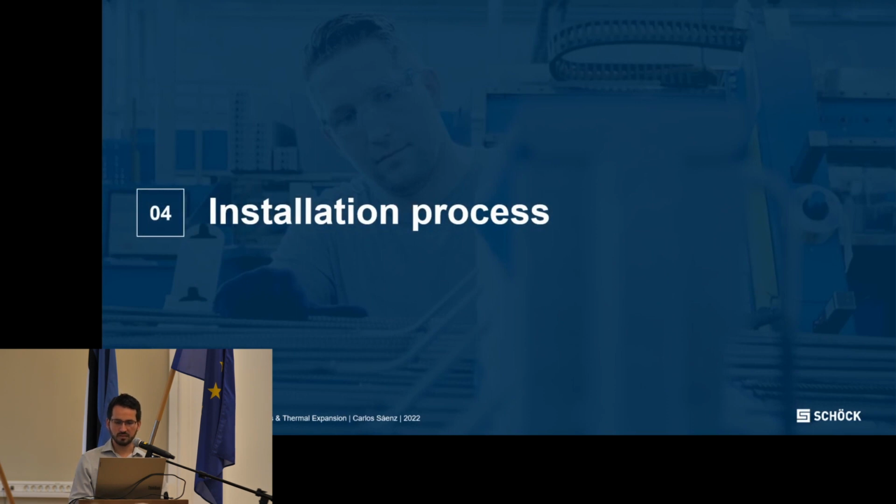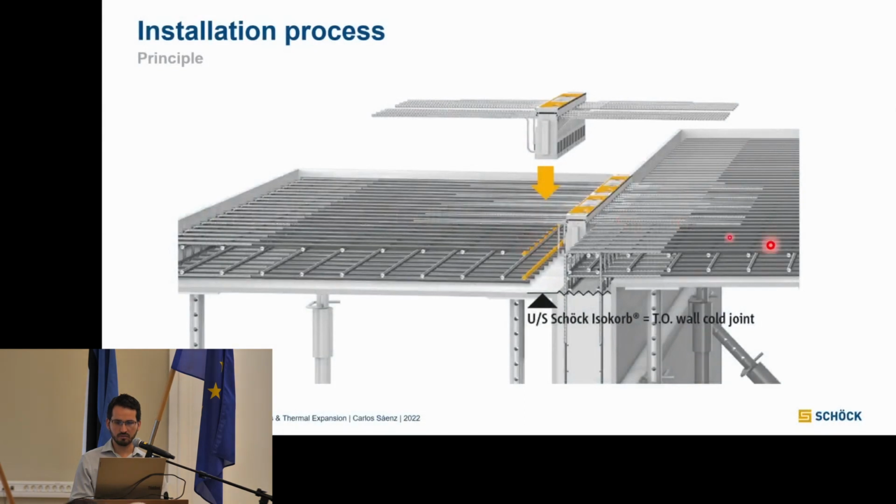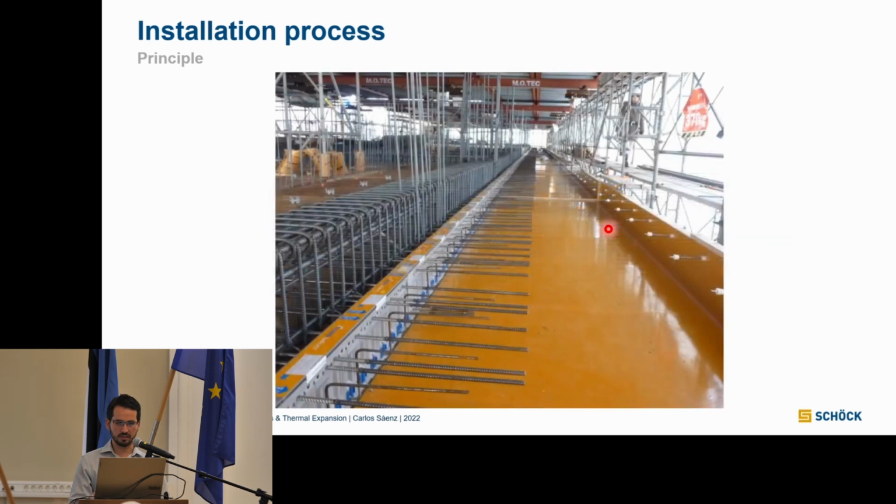Yeah, installation process, just a couple of words on that. This is how you install it. The principle is pretty simple. Once you have all your rebar on both sides, you just wait until the end and place it in place. It has what's called a tongue and groove, so you can put them together. This is what I wanted to point out: you can install it even after you have all your reinforcement ready. So usually construction companies like that because they can put it at the last minute.